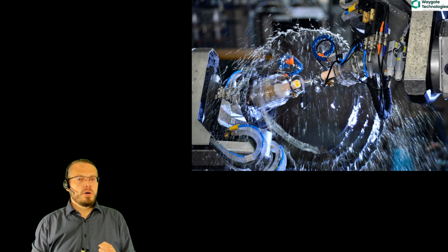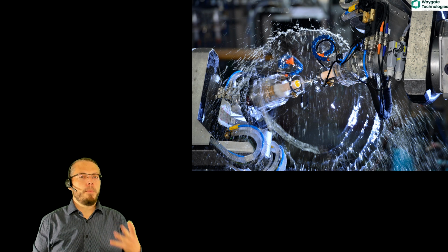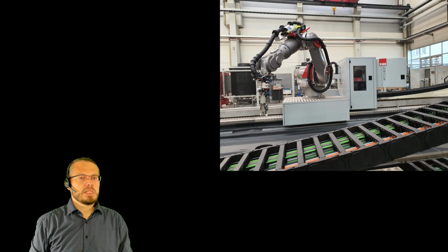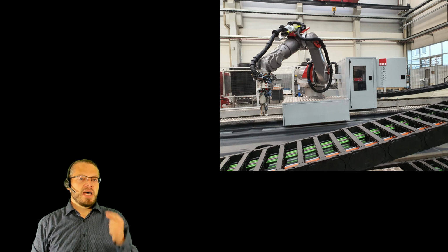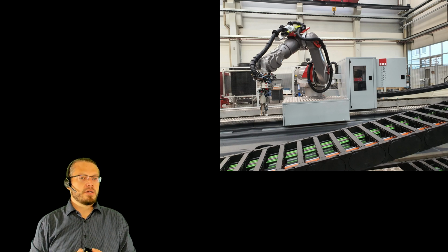With this technology, what is really fascinating, we can then use robots and inspect very complex shaped components. We can also do dual robot systems, so instead of doing a pulse echo mode, using a through transmission mode. This is another example of a robot-based system where we have this 6-axis robot and a 7th axis for tilting the ultrasound at the end. And this is another example of such a dual robot system, and you can see how complex the shape of such a component is and how those two robots have to move together to give a decent result.